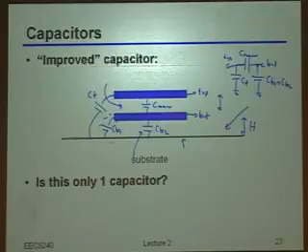Like if you put polyester in a different dielectric process? Oh, I see. Okay, so we'll talk about this actually in 1 second. You basically said, if I can increase the dielectric constant in between those two capacitors, that would be good, right? That would actually increase my main capacitance. Or equivalently, for the same size of main capacitance, would give me a smaller bottom plate parasitic. Now, unfortunately, that's kind of set by the process. So by design, I may not be able to do that.